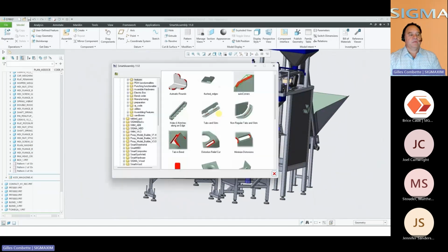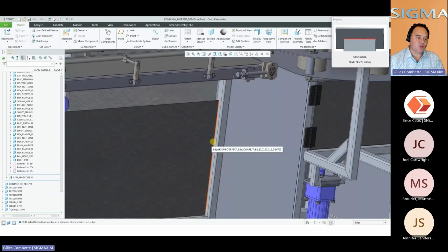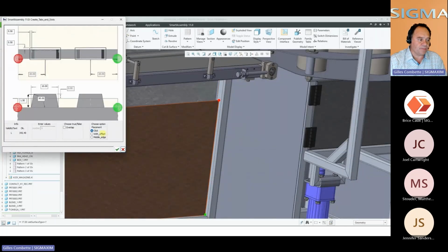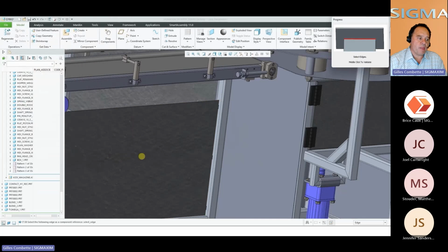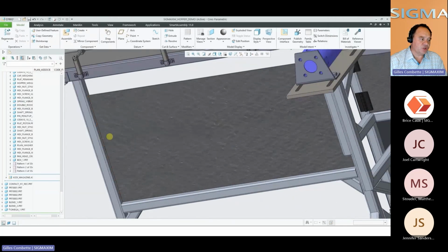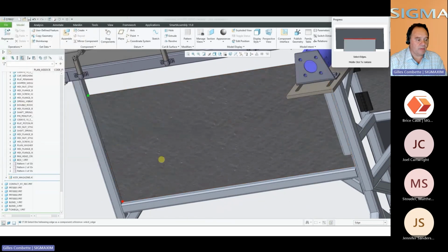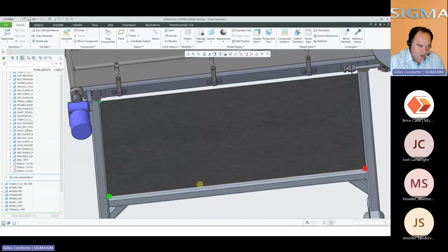Another typical way of placing components before welding, for example, is just to add tenon and mortise, like some tabs that go into rectangular holes. That is made just to hold the part in position, maybe just to hold it before you weld, or maybe just to hold it forever, whatever.